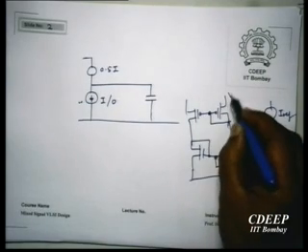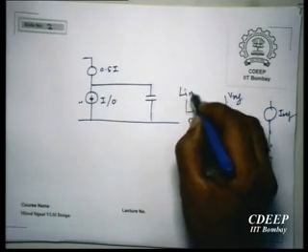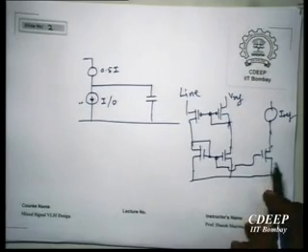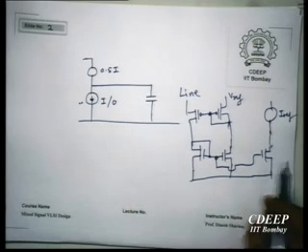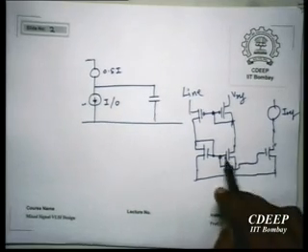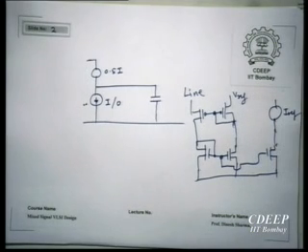So this is the beta multiplier. I have my Vref here, I have the line here, and this current is just being mirrored in this. Okay. Now by adjusting this ratio and choosing the appropriate value of Iref there, I can, so notice that the line current has not changed. Line current remains the same, but the comparison that I am doing is on a scaled up amount of current. Therefore, I can make a compromise between speed and power to any extent.